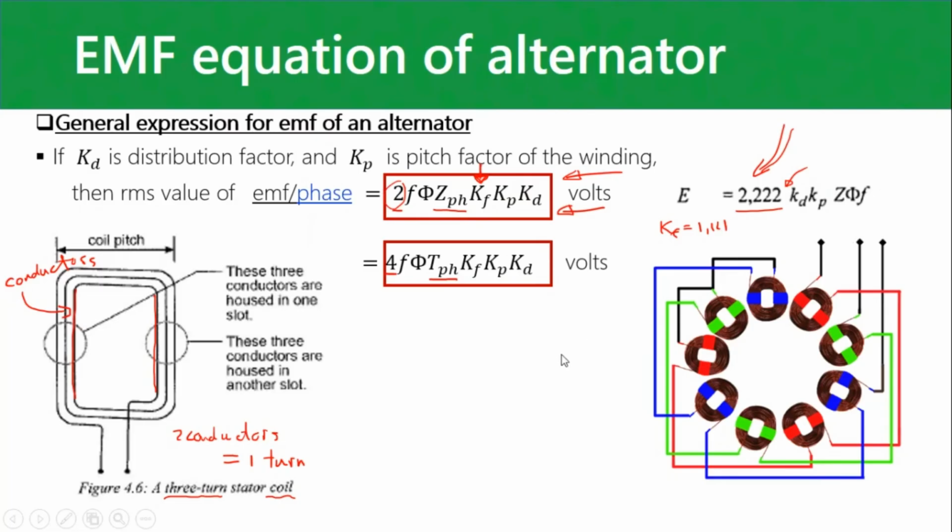So you see why that stator winding looks like it does. It's got all of these coils. You take one phase, the blue. It'll do that, then it'll have another one there, and then another one there, and let's say that's your blue phase. That's why there are so many coils on there. The more conductors you have, they're all in series, it builds up this total EMF or terminal voltage on open circuit.